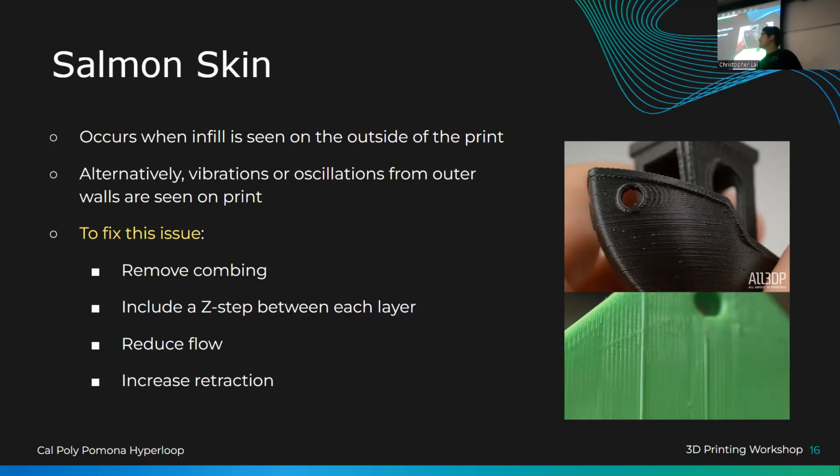It's like saying my printer has a certain precision, for instance my layer height precision is 0.001 millimeters. Whereas the Crealities are 0.04 millimeters, meaning that if you give it any number in between that is not divisible by 0.04, the printer is not going to account for that. It's just going to print whatever is closest.